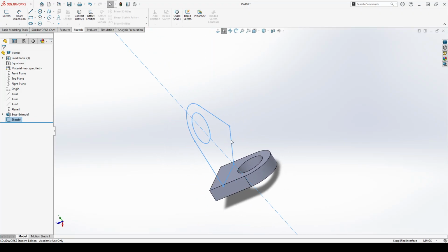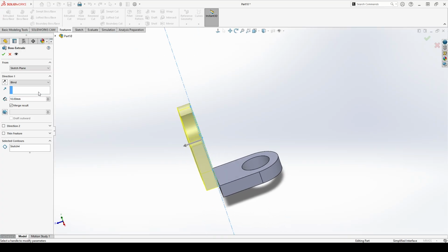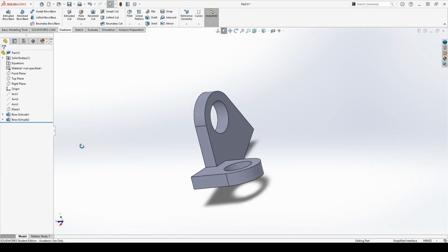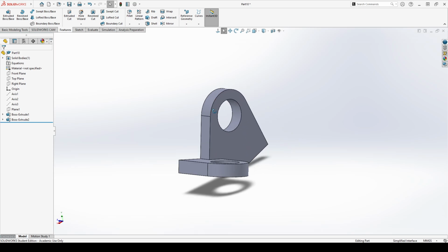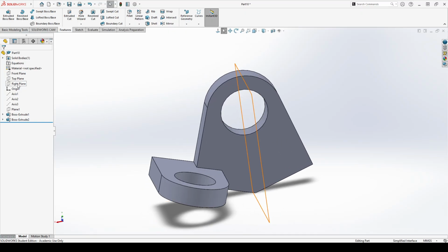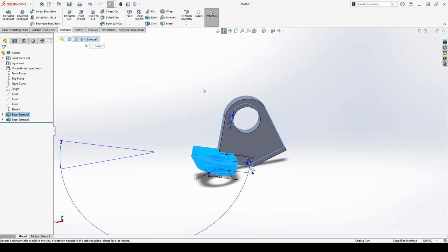and pad it out. Let's go to features, extrude both, and pad out by 10 because it's TYP and it's in the opposite direction. There we go, perfect. Now that we have something existing here that we can mirror about and place on, then we can do this mirror application. So let's make that plane visible first. Or do we even need to make it visible? Doesn't matter. Just choose this item, that thing that we need to mirror, and click on mirror.